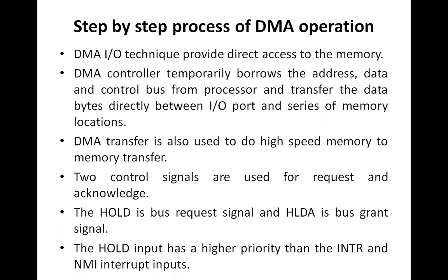Now, this HOLD input has higher priority than the INTR line and the rest of the interrupts of the 8085. The HOLD has higher priority than the INTR line, as well as all the other interrupts, that is RST 6.5, RST 5.5, and RST 7.5.